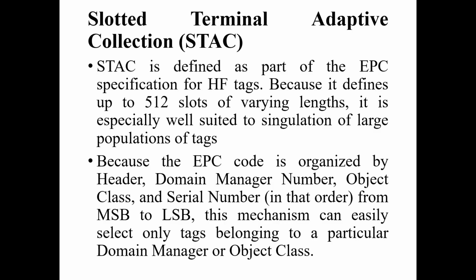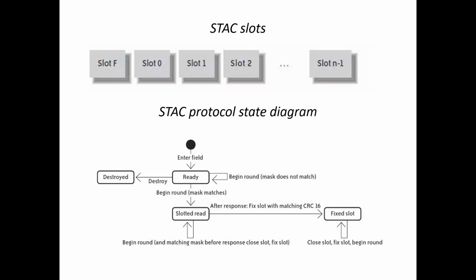Slotted terminal adaptive collection (STAC) is a type of anti-collision protocol like slotted Aloha or binary tree. It is designed to read tags efficiently in slots while reducing the collisions. Here is the STAC slots. This diagram is divided into two parts, that is STAC slots and then the STAC protocol state diagram.